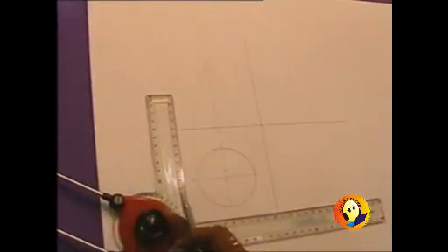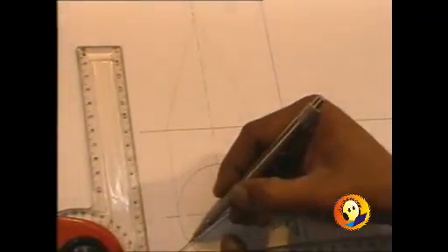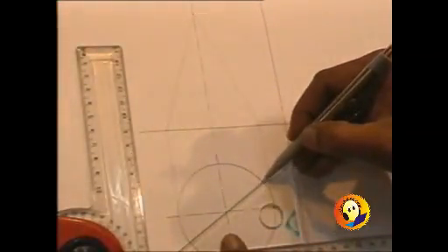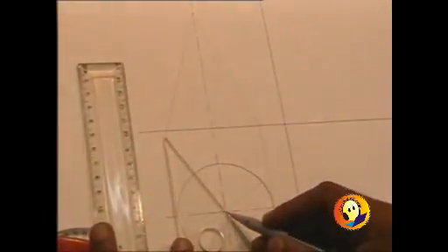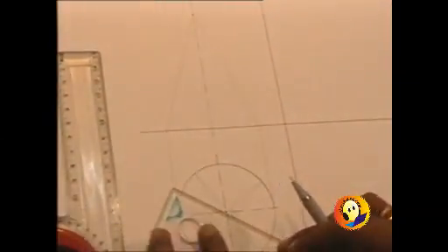So in this case, we will be again starting with the top view, and the circle in the top view should be divided into 12 parts, but this time we will be joining them because it is a cone problem. We are even required to join each point of the base to the vertex.